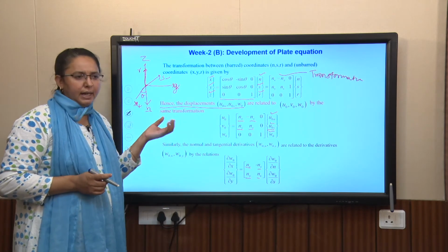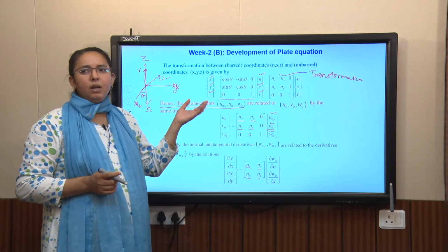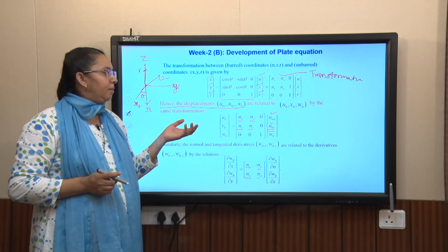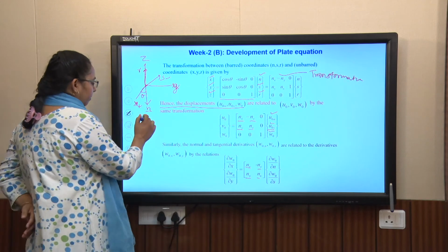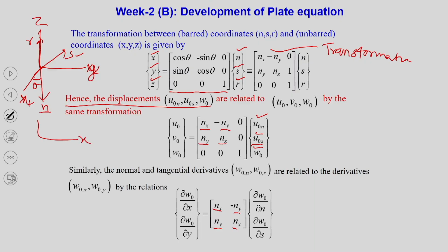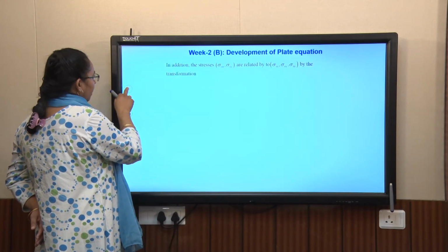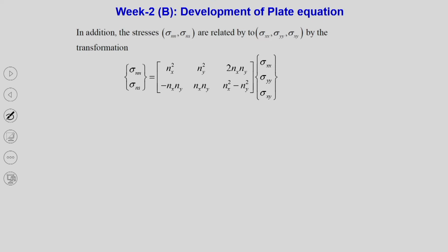I think in the second or third semester, if you go through an AutoCAD course or any MATLAB program, you see how to transform a two-dimensional xy, where xy becomes x dash and y dash if the angle is theta. So, instead of that you are saying the cosine vector, where cos theta is nothing but the cosine vector nx, and sin theta is nothing but the cosine vector ny. Now, the transformation for the stresses.